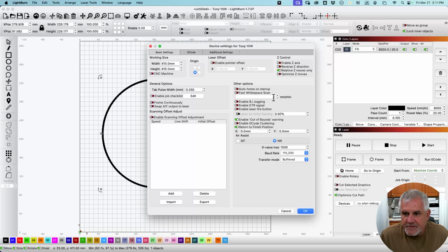And here you set the speed. So like if your laser has a maximum speed of say 9,000 millimeters per minute, you'd probably want to put 9,000 in there, and you may only be engraving at 3,000, but in those large blank areas it'll speed up to 9,000 to go across them because it doesn't need to be burning.